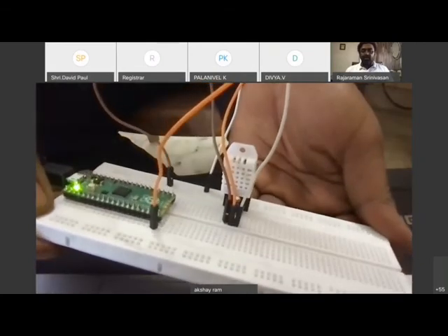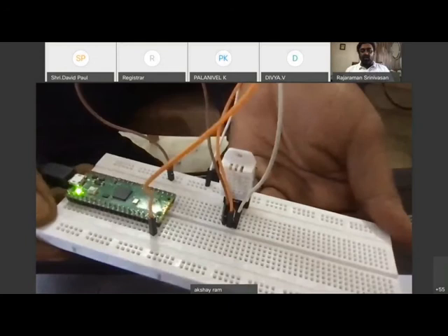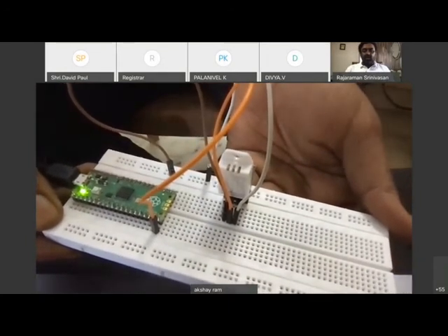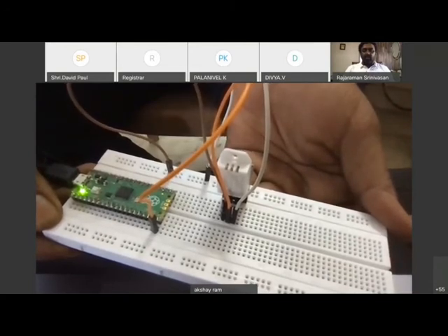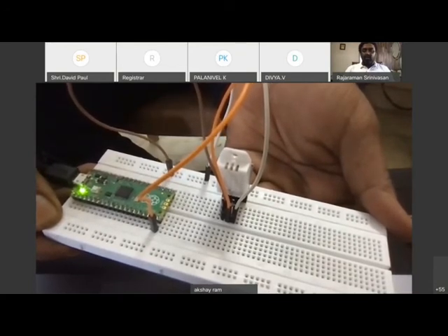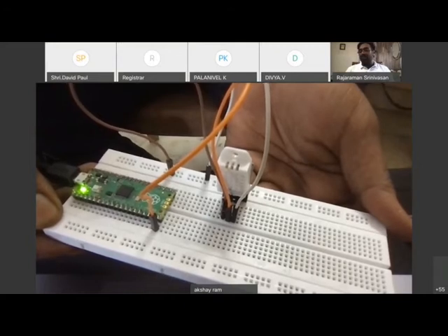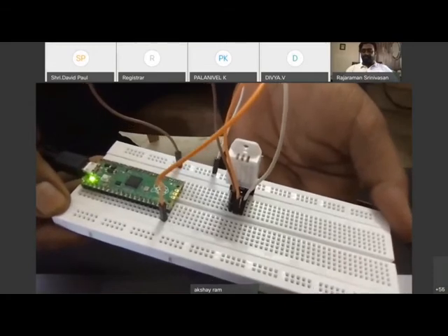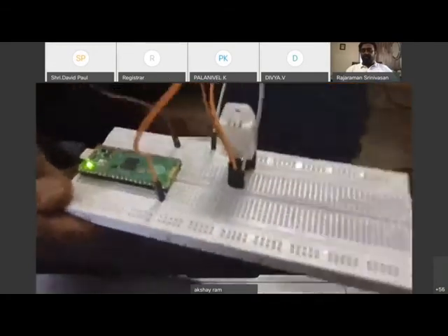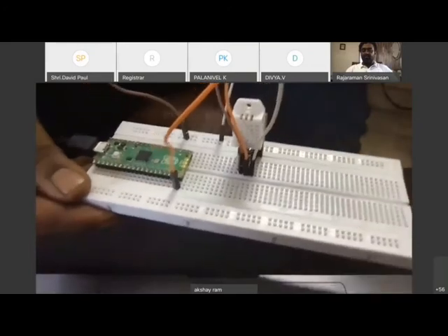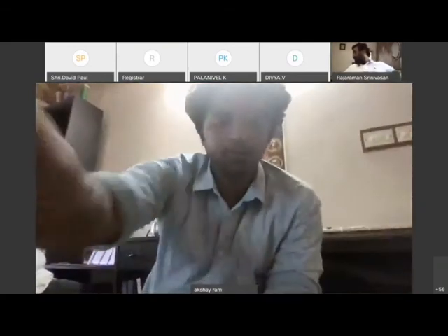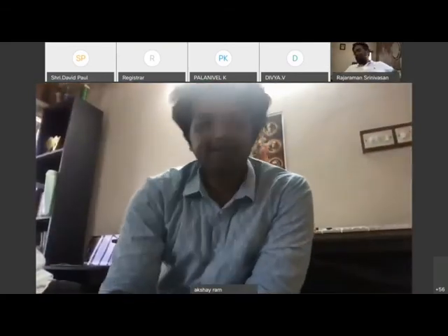With the camera, so you can see. Yeah. So the one on the left-hand side is the positive. The one in the middle, the orange wire, is the data, and the one which is white is the negative. So this is how it needs to be wired. So we can just plug this for now. This is a very simple wire. Only three things to be connected.